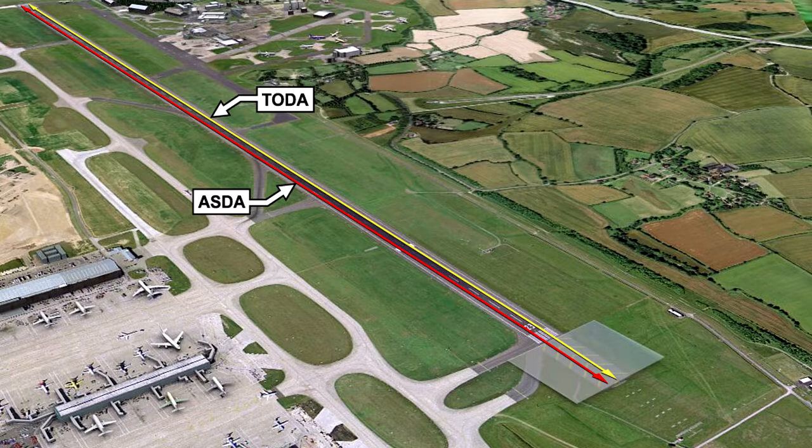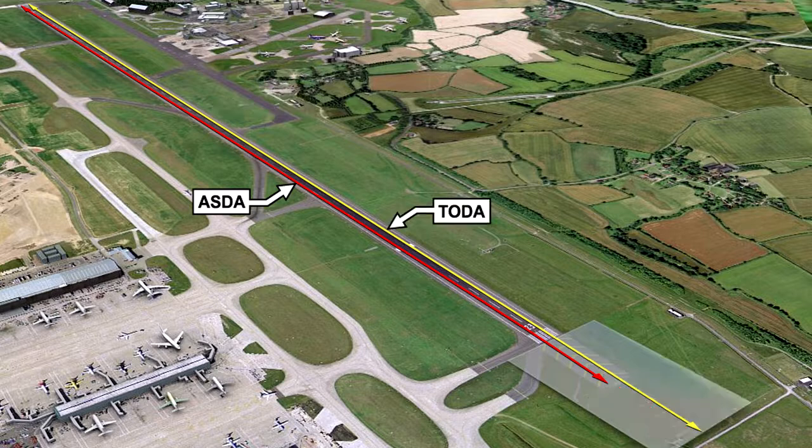The term is used because many takeoff performance calculations can be simplified by using balanced field lengths. We will consider balanced fields when dealing with takeoff in the Class A section of this course. When the TODA and ASDA are not the same lengths, as in the case illustrated here, we are dealing with what is called an unbalanced field.